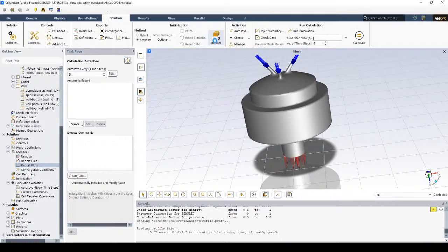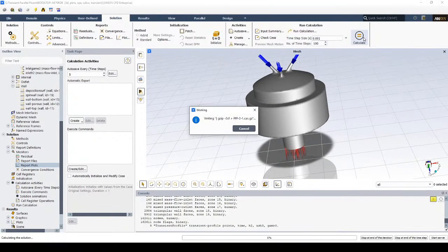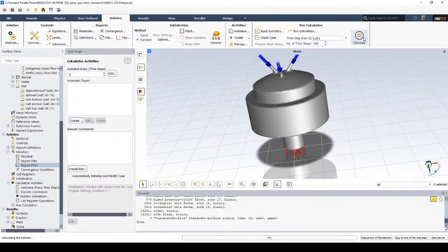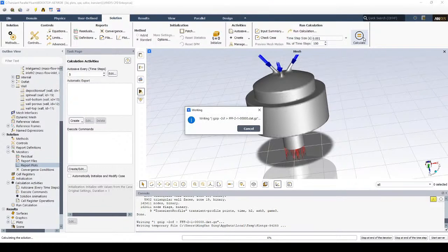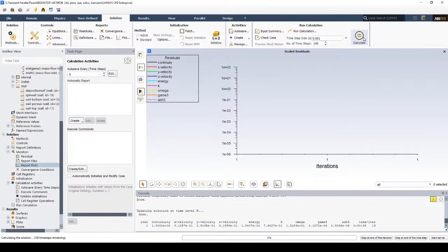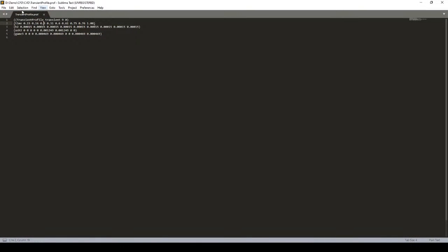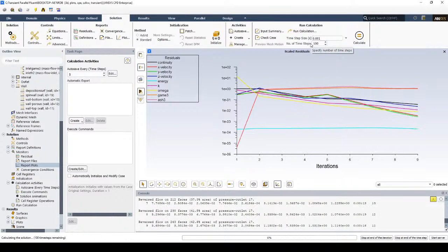So standard initialization, and a typical time step is like 0.01, 0.001. So we can run 100, 1,000 time steps. This whole thing doesn't last very long, so we can go back to the amount of time it's going to take to run the whole simulation, the physically defined transient simulation time. I guess we want to look at our table here. So the maximum is 1 second. So we really want to run a second of the simulation.